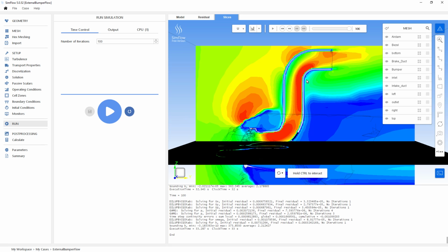And as I look at this, I would say, well, I probably don't want to use a 90-degree bend here. Maybe something like a 60-degree bend would be able to help with the flow of air because we've got a low pressure system right here and high pressure right around those corners.